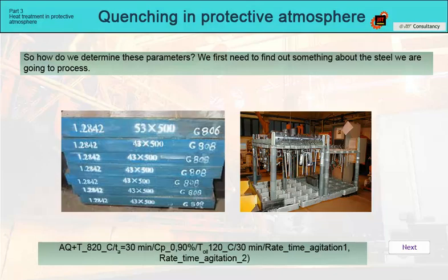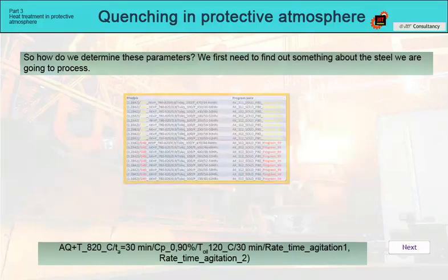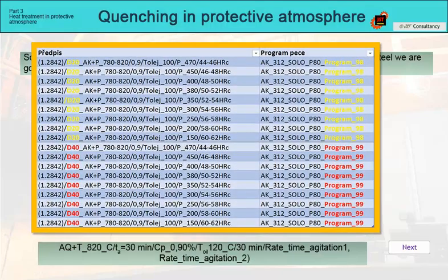It looks complicated at first glance, but in reality, since the heat treatment plant usually involves repetitive activities, we select the work instructions from the archive of previously performed processing, and the furnace program is also stored in the furnace memory. The table shows a set of general routings for material 1.2842 for various dimensions of parts.